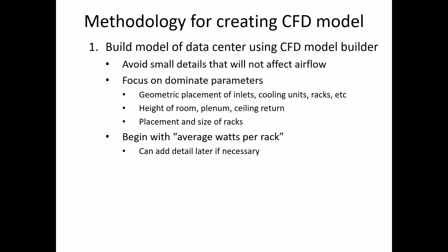And a few notes about creating data centers. Just again, for new users or my users, avoid small details. It is not a CAD system. One of the things that I run into with new users is they want to put everything in it. And you can learn a lot with a fairly coarse model about what's going on in the room. You don't have to put every little tiny thing in the model. If later on you want to add details to see if they make a difference in the results, it's easy to do. So focus on the big stuff.